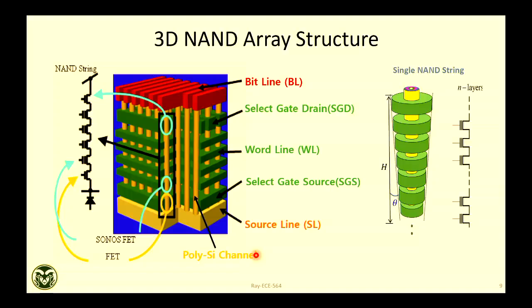You heat the silicon at a very high temperature, like 1000 degrees centigrade, and that's why it is costlier. Because when you want to make it crystalline, you have to change the crystal structure. That requires a very high energy-intensive process. So you make a crystal in a mold like this, and then you sell it by cutting it into wafers. That's why a wafer looks circular. So that is the crystalline silicon process.